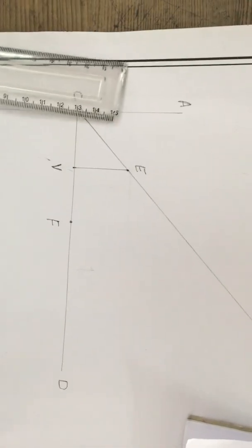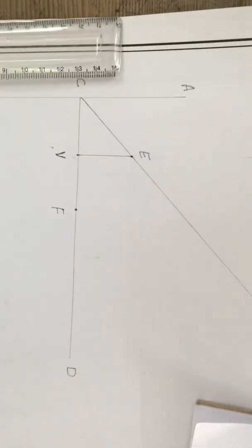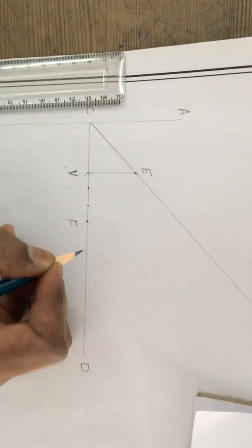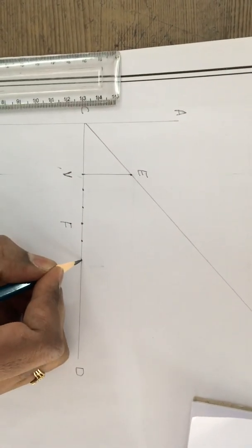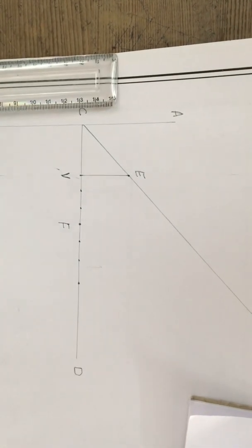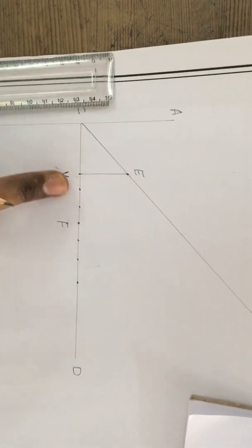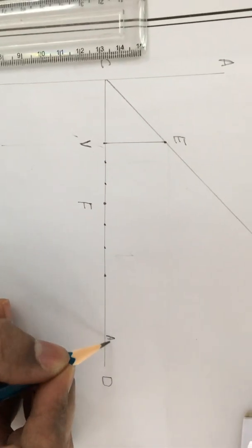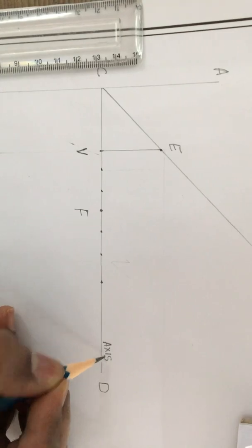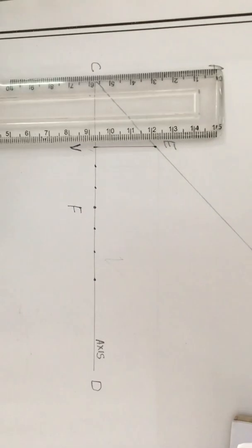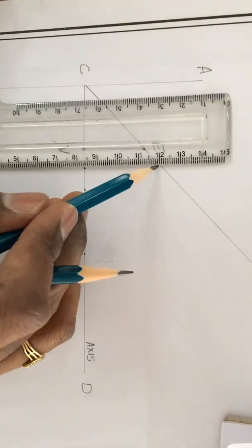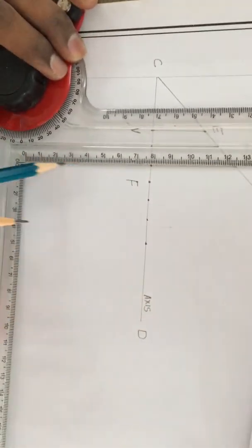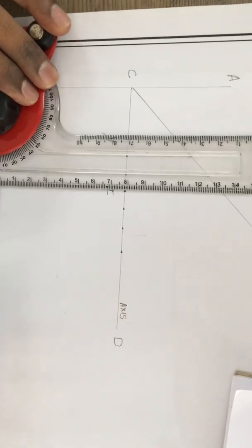Now we are supposed to work out a general construction where we divide the axis line into any number of divisions that need not be equidistant. What I am telling is, next to the vertex, divide the axis line into any number of divisions that need not be of equal distance. Later, drop the perpendiculars from the VE line to the axis, from all the points. If you want, you can even select the focus.